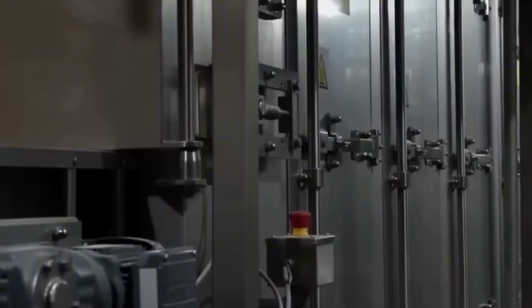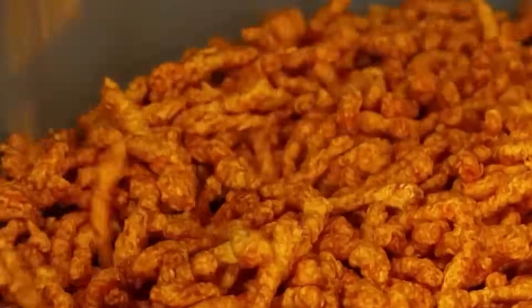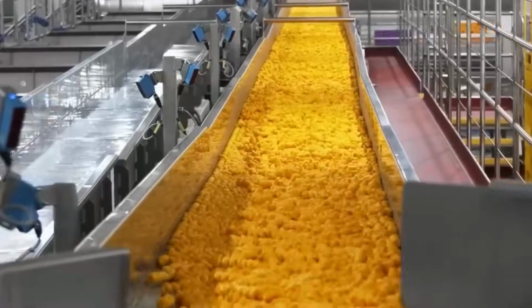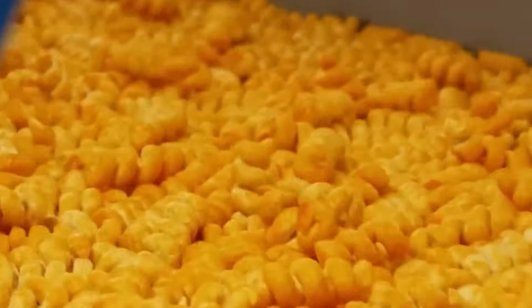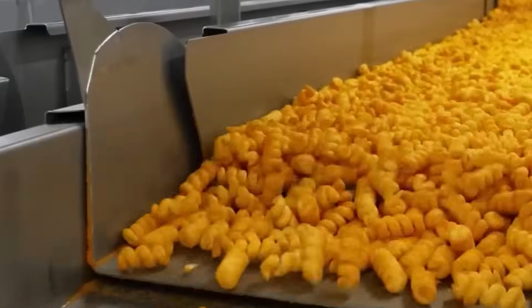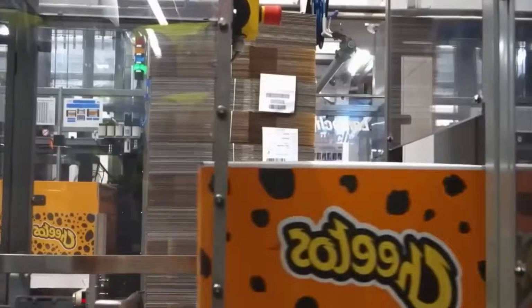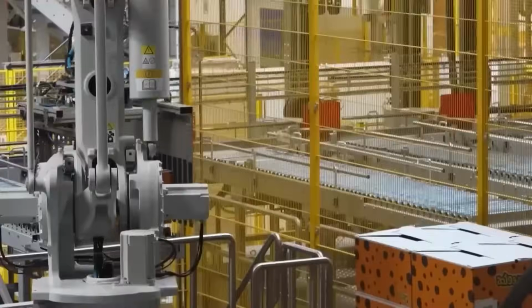For crunchy variants, the base extrudates are fried in a continuous oil bath system. The fryer is filled with vegetable oil, commonly corn or canola oil, maintained at 170 to 190 degrees Celsius, using heat exchangers and recirculation pumps. The extrudates enter on a submerged conveyor belt that keeps them fully immersed for 30 to 45 seconds. During this time, surface water evaporates, and the structure is locked in through rapid dehydration. Oil absorption is measured using inline sensors and confirmed by batch gravimetric analysis.